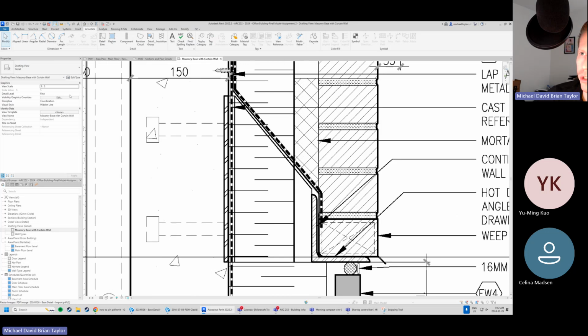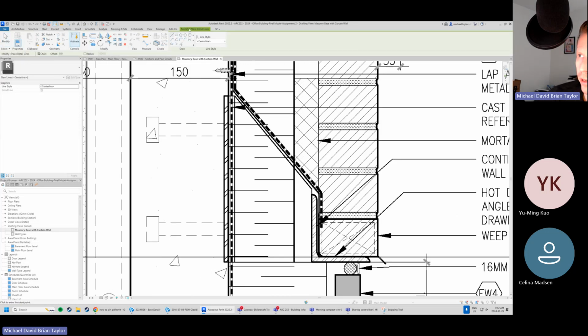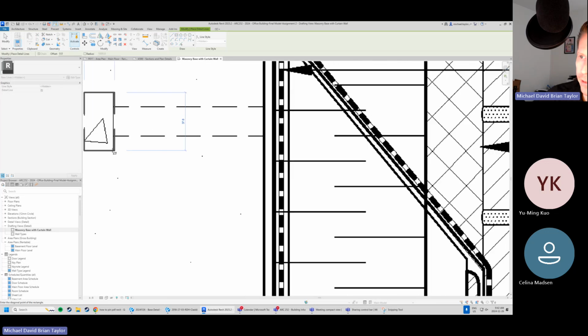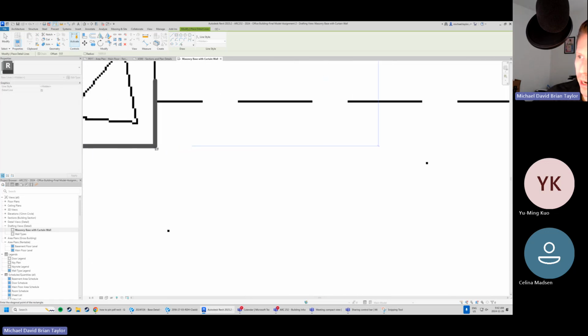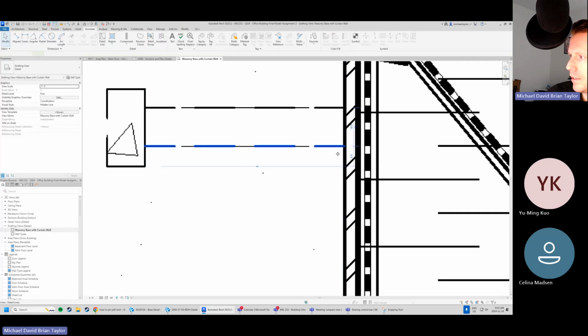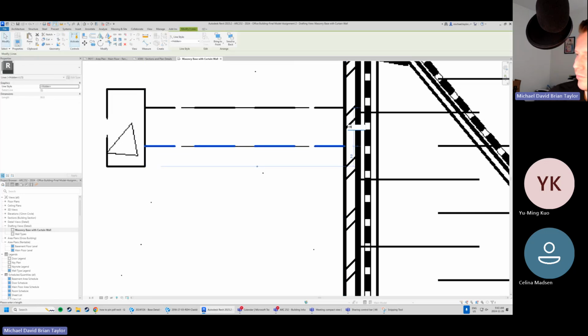Some other things we might want to do are these detail lines. So I'm going to grab detail line. I'm going to do hidden. Hidden means that it's beyond in the view. So these are little anchor bolts embedded inside of the concrete. These don't have to be perfect. I think when I drew these originally, they were 38. Oh, they are 38. Okay, 38. This does not have to be perfect. And then just tie them. That's 19, which is half of 38.